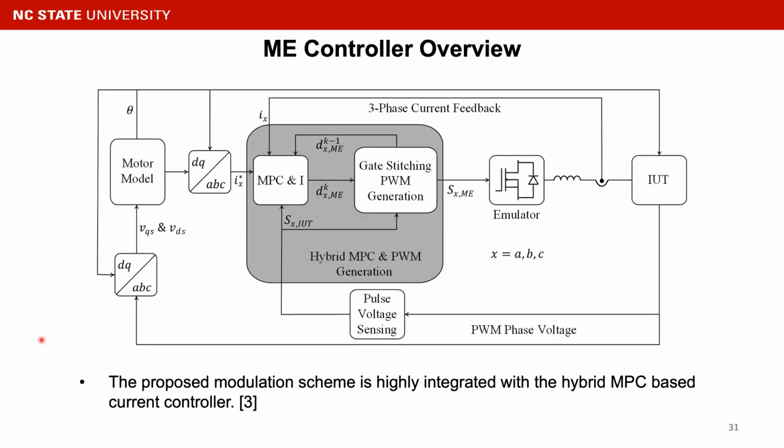Now let's look at the motor emulator controller. As we mentioned before, this is a hybrid model predictive controller, and the controller is running in the alpha-beta stationary frame. The hybrid controller is highly integrated with our newly proposed PWM strategy.